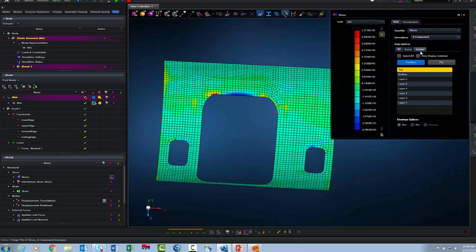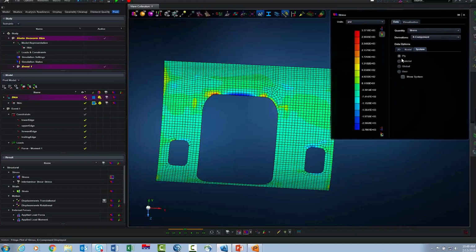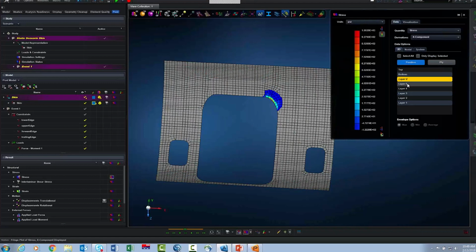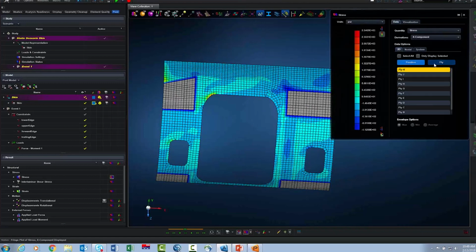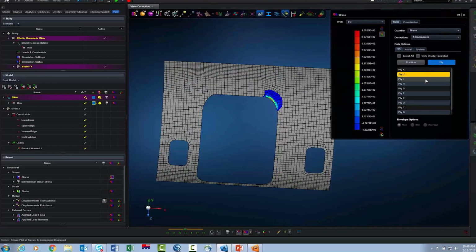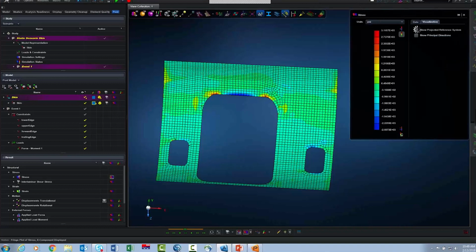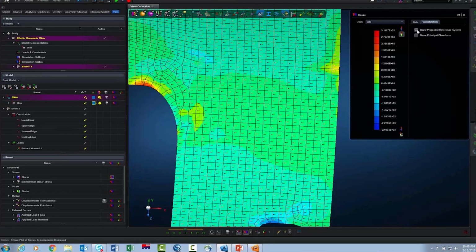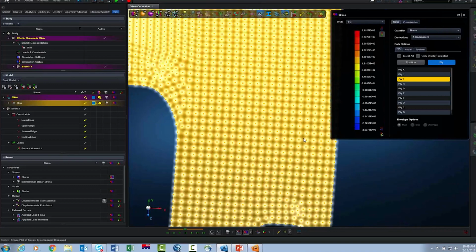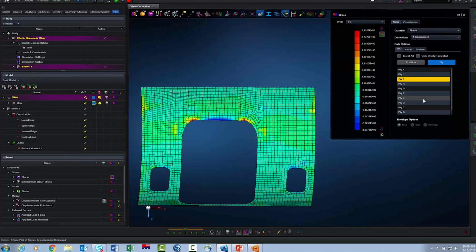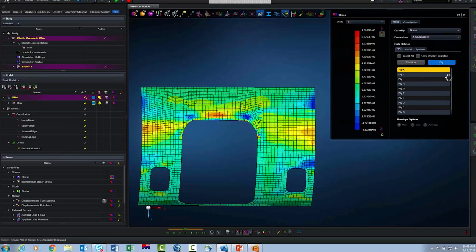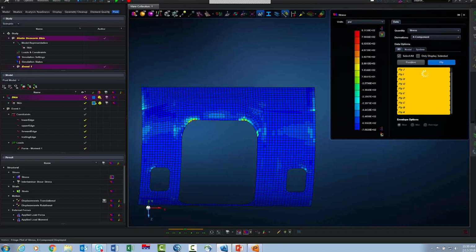Okay, and I know that I'm looking at sigma x because I can go to the system and I see that I'm looking at the ply material orientation versus material, which would be the material axes for the panel itself. Okay, I can look at results for the individual zone layers, or I can also look at the results for the individual sheets or the individual plies. If I need to remind myself of what the material orientations are, I can quickly do that as well. So, you know, I don't have to go very far to actually see what the material orientation for this ply is.